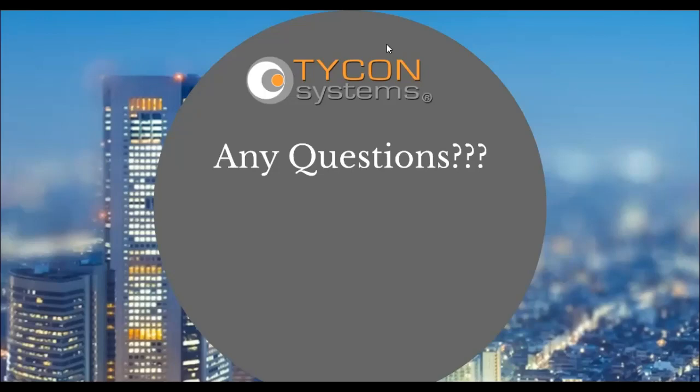All of our MPPT controllers will work with any type of battery. So if you have lithium batteries that you can source locally, we can design a system that doesn't include the batteries, and you're able to connect to the MPPT controllers. Benefits of lithium: they're much lighter weight and have a smaller footprint, so you can add more batteries, but like I said, they are